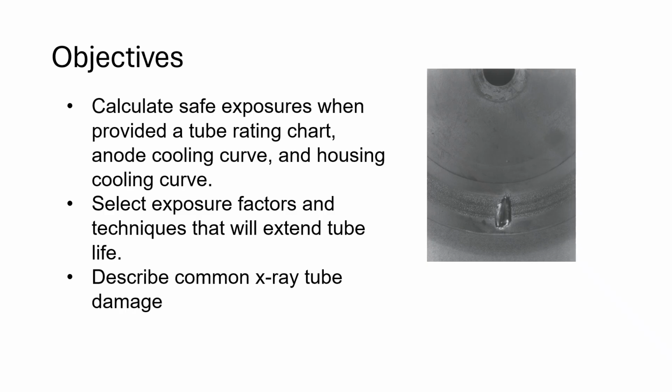You won't be using this on it, but it's important for you to understand what that software is doing and why it's doing it, because you don't want to blow up your X-ray tube. You really don't want to fry the components. And there's three components that are sensitive to heat damage: the anode, the glass housing, and the filament.